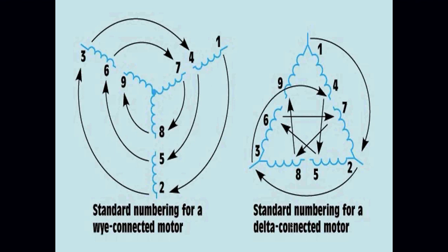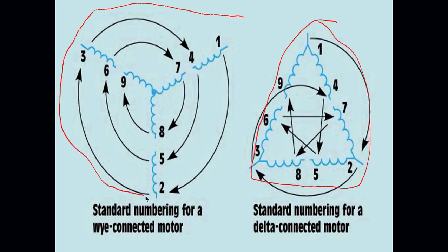When we look at these windings, can everybody see why one's a delta and one's a Y? Again, we have our delta symbol. Over here we have our Y symbol. Now, both of these motors are dual voltage motors. It all depends on how you connect these connections as to what the voltages are.